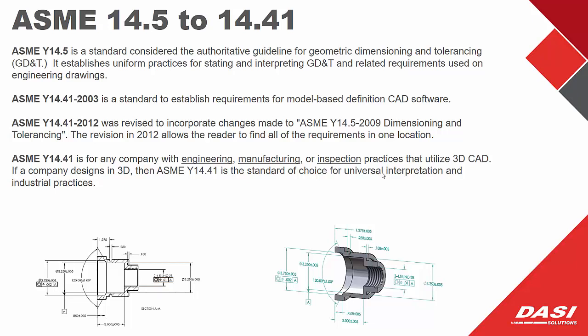Then, as CAD has developed and people started to take more advantage of 3D CAD, people wanted to provide this same product manufacturing information inside of a 3D model. So ASME Y14.41 was developed, and that established the requirements for model-based definition. Both of these standards have been revised over the years, and ASME Y14.41 2012 was revised and basically encompasses all of these standards to allow the reader to find all the requirements in one location.